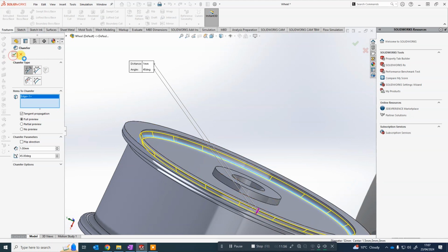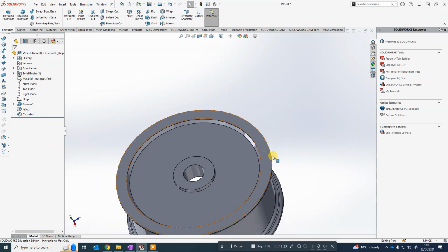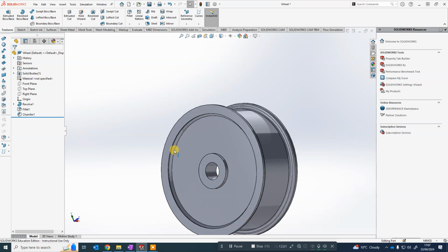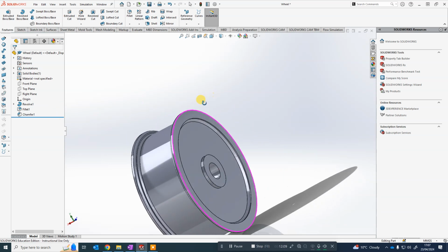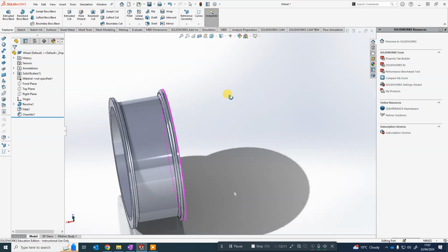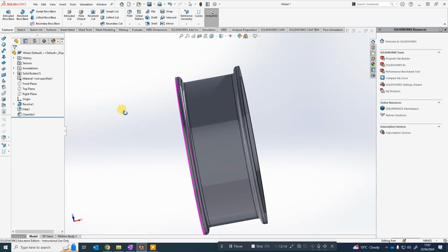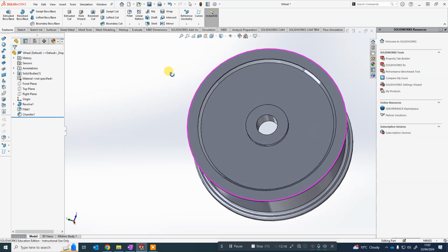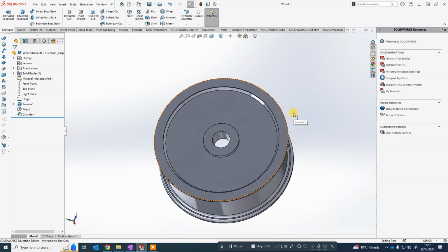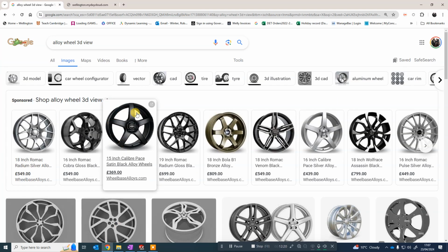Okay, click the tick. If it pops up with any kind of error, it's because the chamfer you've chosen is too big for the geometry that's there. It means it can't physically compute it. So just try changing the number to a smaller dimension and then it should hopefully create it. So this is where you're customizing now. You can put your own chamfer on there, your own fillets, wherever you want them to. When you're happy with that, we're going to move on to making these cutouts.